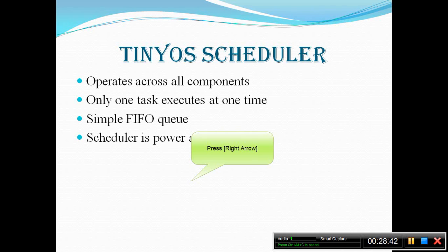If a component needs to post a task multiple times, this slight change in semantics greatly simplifies a lot of component code. So, rather than testing to see if a task is posted already before posting it, a component can just post the task. Components do not have to try to recover from a failed post and then retry. The cost is 1 byte of state per task.